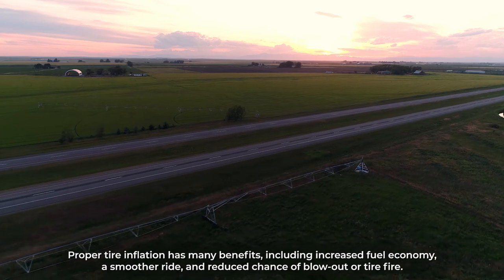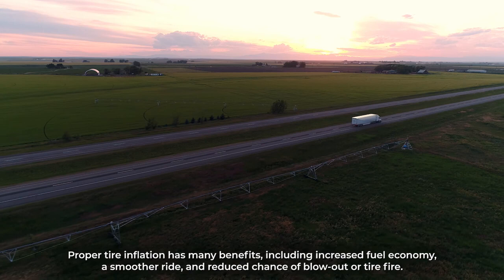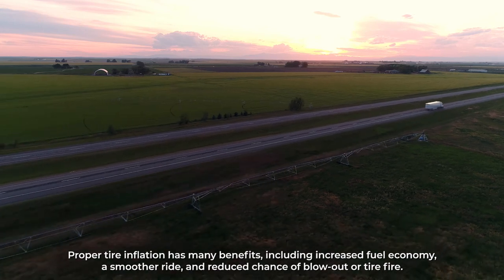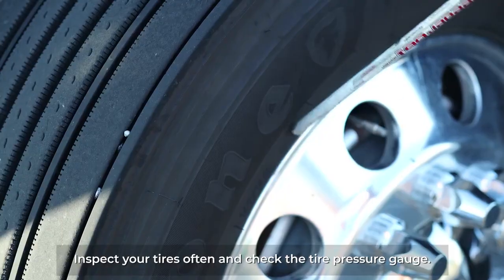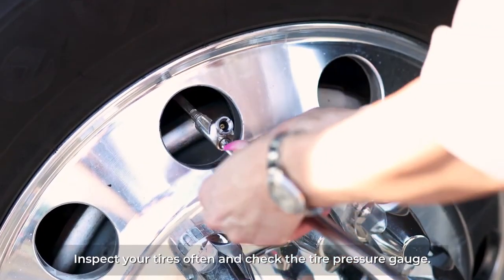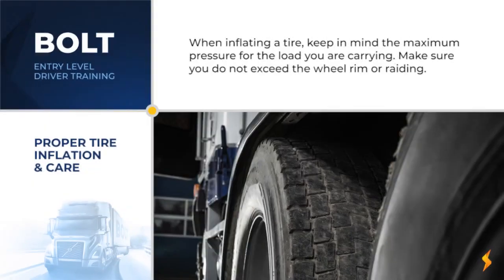Proper tire inflation has many benefits, including increased fuel efficiency, a smoother ride, and a reduced chance of blowout or tire fire. Inspect your tires often and check the pressure with a tire gauge. Refer to the manufacturer's specifications for correct pressure. When inflating a tire, keep in mind the maximum pressure for the load you are carrying, making sure you do not exceed the rim or wheel rating.